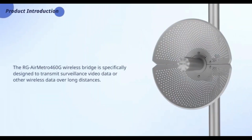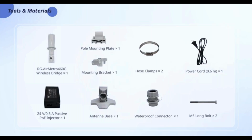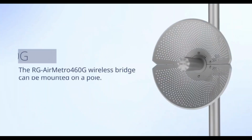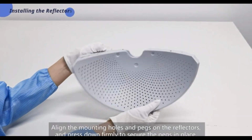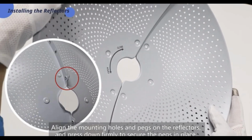The AirMetro 460G wireless bridge is specifically designed to transmit surveillance video data or other wireless data over long distances. Before installation, prepare necessary tools and materials. The AirMetro 460G wireless bridge can be mounted on a pole. Align the mounting poles and pegs on the reflectors and press down firmly to secure the pegs in place.